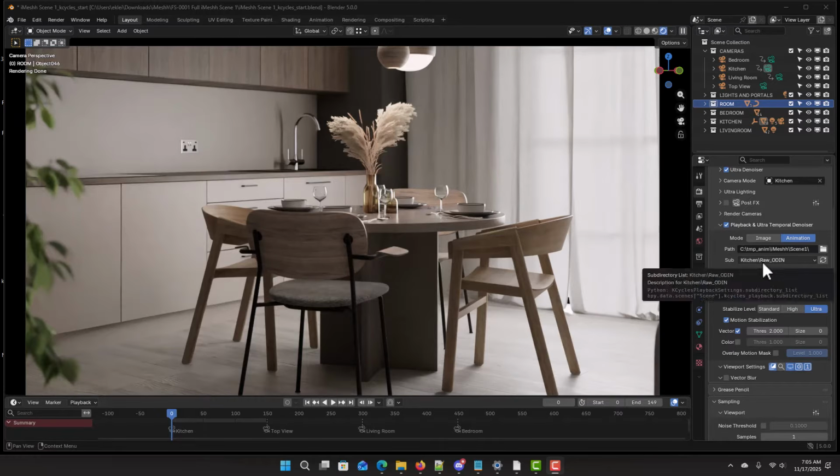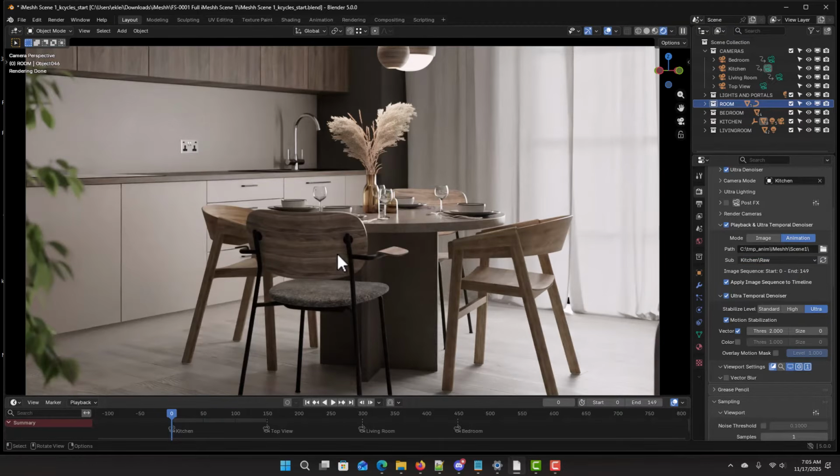Let me switch to multipass, and right away you see it's got texture detail, the floor. You go back and forth. It becomes blurry on the back of the chair and it becomes softer. Go back to multipass. So at low sample rates, the regular denoiser makes the image noticeably softer and with less detail. That's why multipass is recommended.